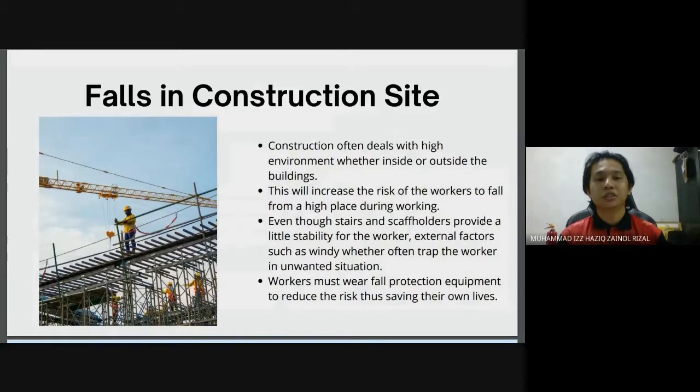So the next one is falls in construction site. Construction often deals with high environment, whether inside or outside the buildings. This will increase the risk of the workers to fall from a high place during working. Even though stairs and scaffolders provide a little stability for the worker, external factors such as windy weather often trap the worker in unwanted situation. Workers must wear fall protection equipment to reduce the risk, thus saving their own lives.